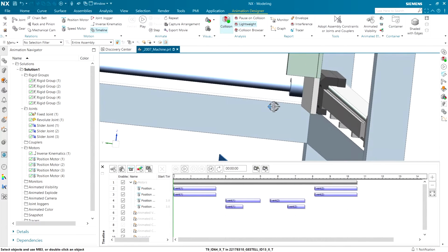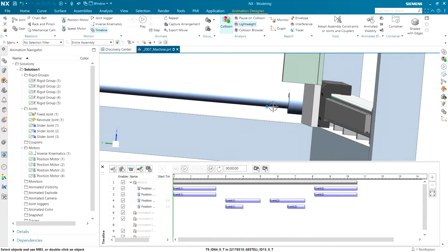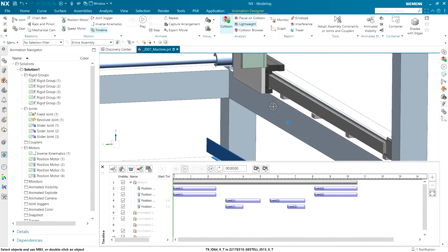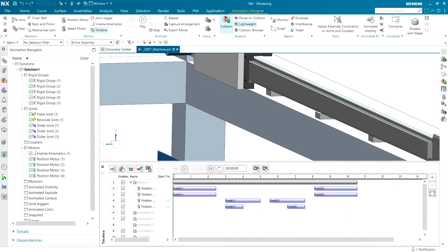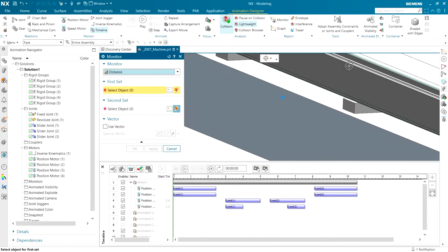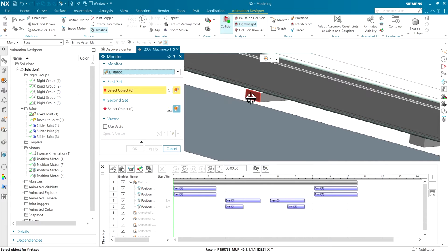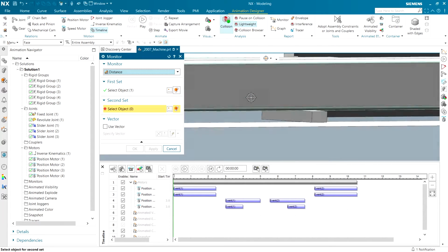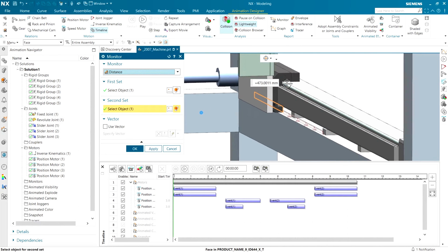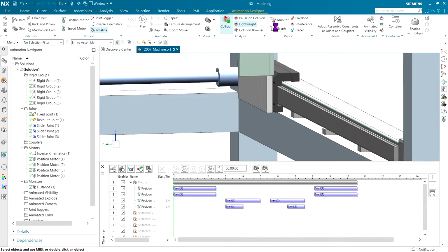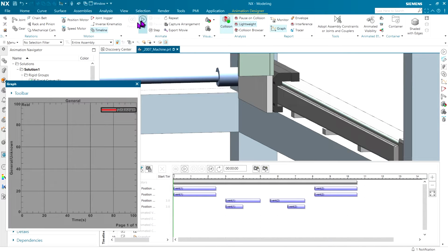These little 2 parts here, one is sticking out probably a little bit too far. So all we need to do is just make a simple change to that and make its length a little bit less. So before we make the fix, we probably want to know how bad the interference is and when we're done. So let's go ahead and put a measurement between these 2 faces and see the before and after. So I'm going to use this little command here called a monitor. I'm going to put a measurement between this face and, if I can zoom around here, that inside face, and we'll take a measurement of that and see what that looks like. We'll plot that on a graph and just get sort of a baseline before we go any further.